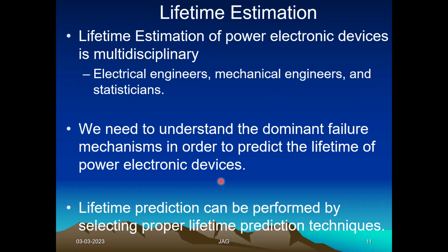So like that, the total degradation can happen if you abuse the devices. If it is a switch, over current, over voltage, etc., can very easily happen. If there is a lightning, over voltage can happen. If there is a short circuit, over current can happen. Such phenomena are very common, but it will not fail the device instantly.